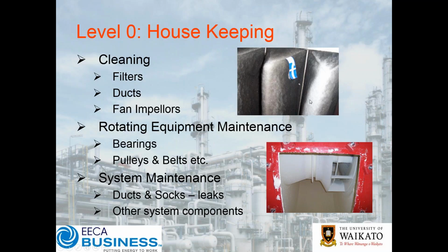Obviously, a food plant might have a more stringent requirement than, say, a low-level extraction plant. However, on an extraction plant, if you're extracting, say, sawdust or some other material, a build-up of that material in ducts can be a major safety hazard and fire risk. So there are a number of things that you probably need to think about.